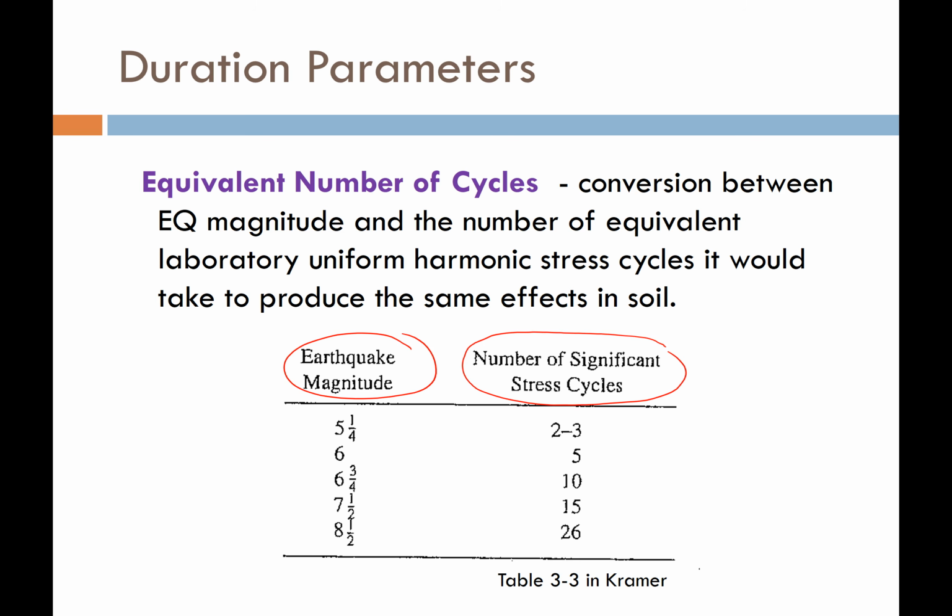So if we have a magnitude 8.5, for instance, we would expect that earthquake to last a pretty long time. You can see it's the equivalent of 26 cycles in a cyclic triaxial test.